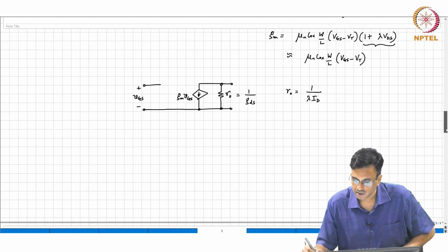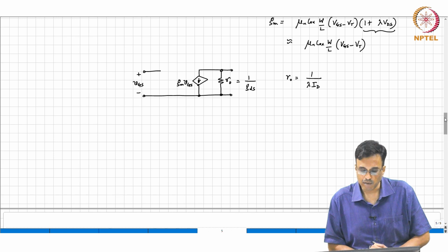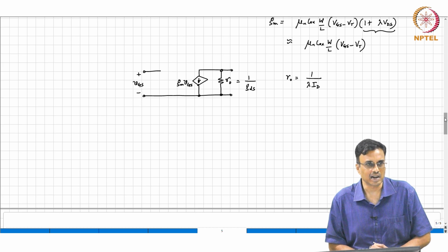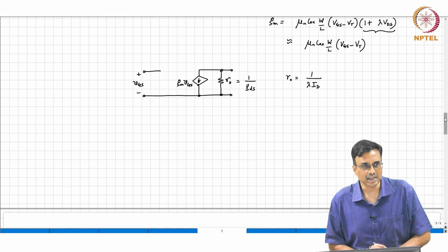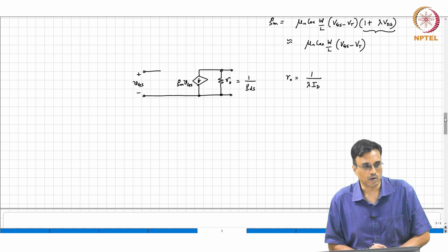Alright. So, now the question is: it seems like all along we have been working with an ideal transistor model which does not exist anyway. So, we now go back to all our circuits and start figuring out what happens when the output resistance is finite. Earlier the transistor was an ideal incremental voltage controlled current source, meaning that the output impedance was infinite. Now, it is not infinite after all, there is some R.